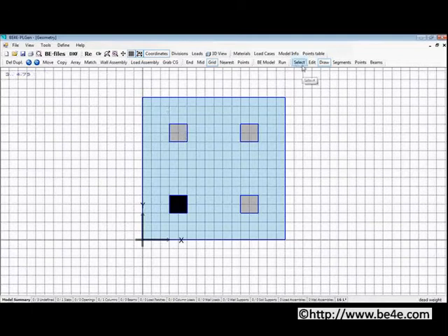So I'm going to go to the select mode. I'm going to choose the newly drawn objects, click on match. Now obviously nothing appears or nothing happens, but the command has been activated. And I'm going to choose the defined column that I have. I'm going to click on it, and the 3 newly drawn objects have become defined, and they will have exactly the same properties as the column over here. Now this concludes tutorial number 4.